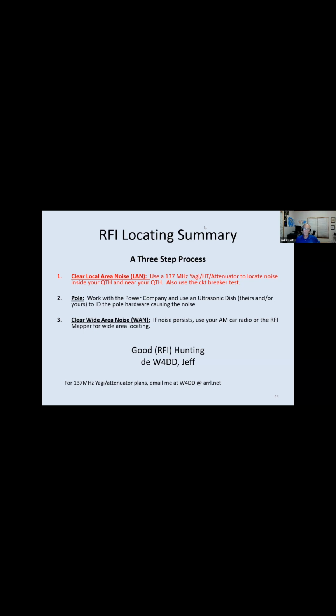But other than that, they don't care for the most part. I mean, they kind of view that as, well, it's been around forever. Nobody's complained about it. We're not going to be too proactive and go out and find every single arrestor that's making noise. And I think you have to kind of look at it from the standpoint of there's lots of small noise sources, and we probably don't care a whole lot about those. But some of the bigger ones, like that one where we had the bolt arcing to a metal plate, that would have been a safety issue eventually, but it was loud. And usually the really loud ones are the ones they need to pay attention to.